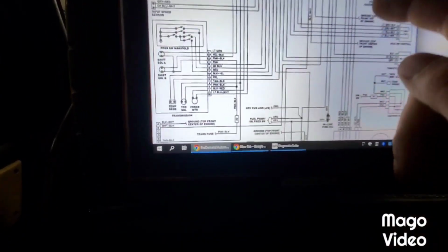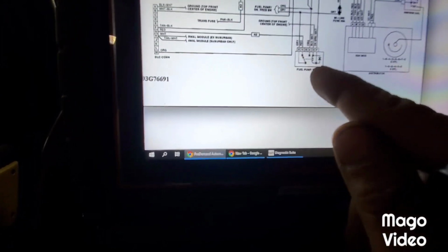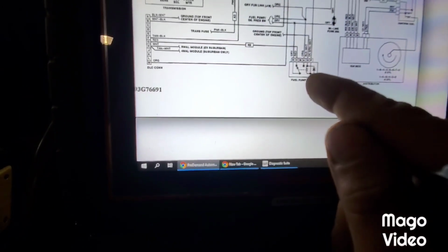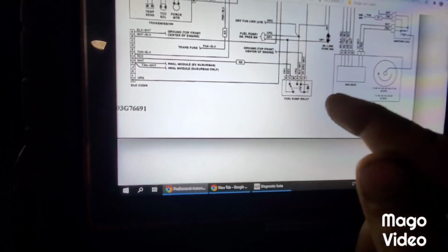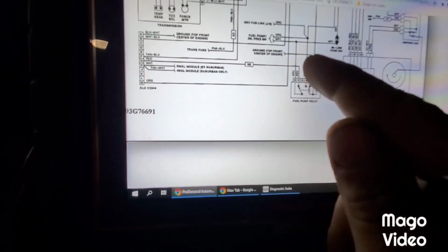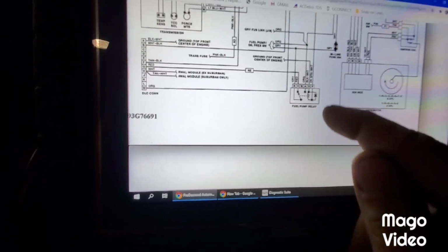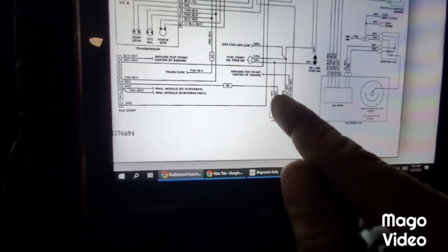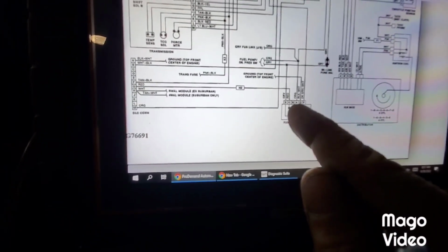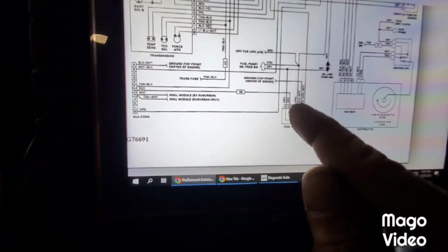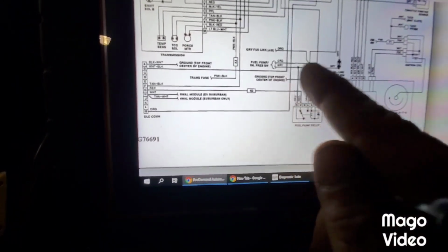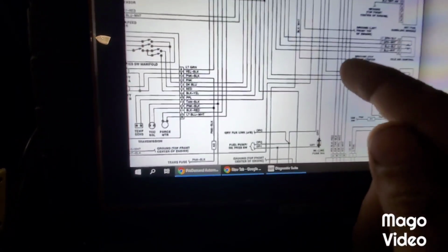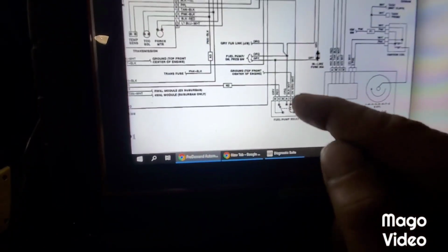So I would say, guys, the easiest way to test this is going to be to go to the fuel pump relay. And what we're going to be looking for on the switch side is that power feed. Now, I don't know where this lives, but I'll find it. And I apologize for the length. I'm just trying to look at how this is designed.